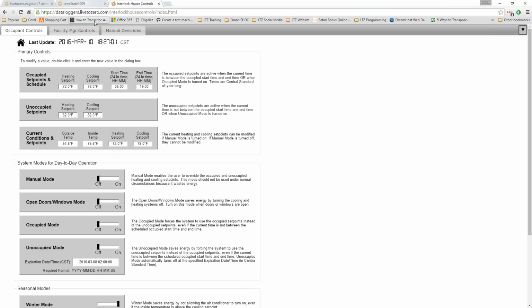So as the outdoor temperature changes, so recently it's been mild, in the middle of the winter it's not, the appropriate start time when we should turn that temperature set point back to 72 could be right now. The past few days, it's only taken a little while for the house to heat back up to 72. First of all, because the heating system is not fighting with the heating load caused by the low outdoor temperatures. And secondly, the building itself is not getting as cool overnight.